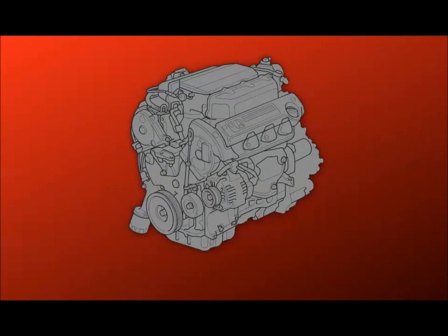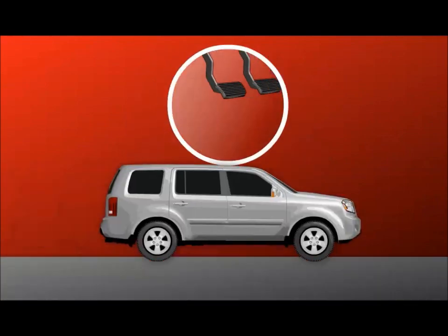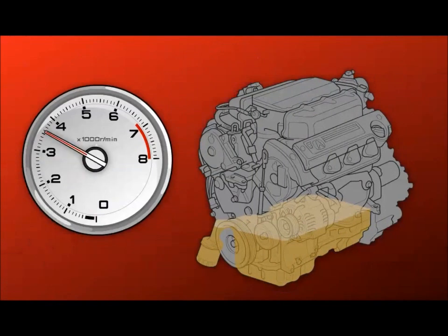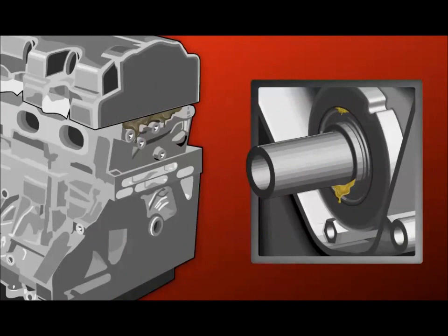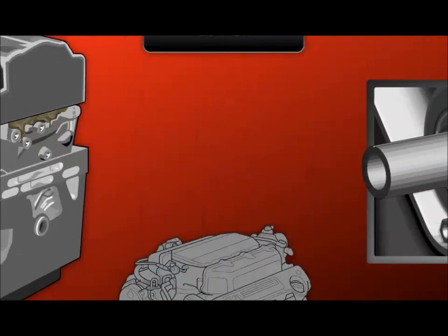Excessive oil can also cause idle vibration, power loss, or even limit engine RPM. Finally, excessive engine oil may increase crankcase pressure, forcing oil out of the engine through seals or gaskets.